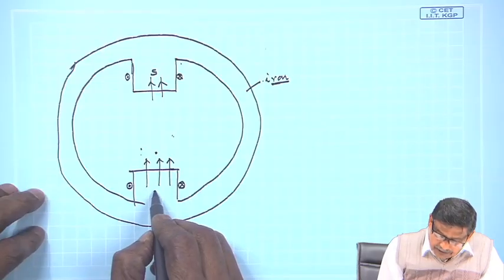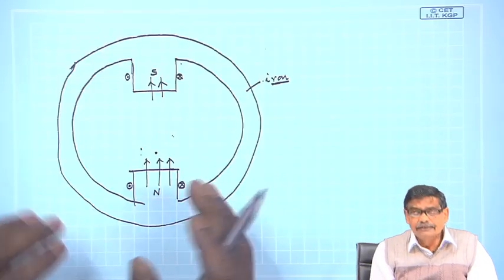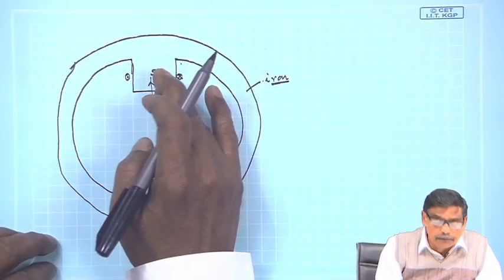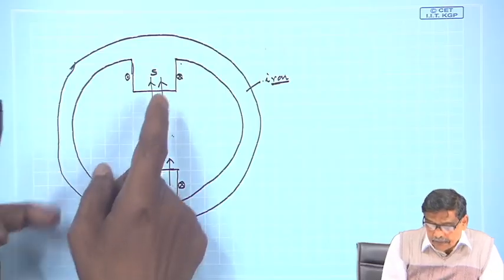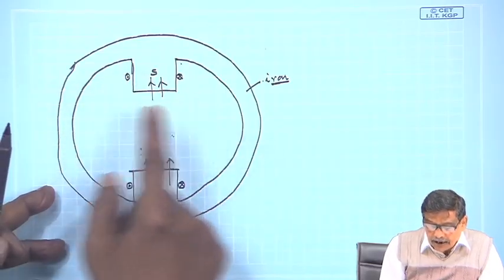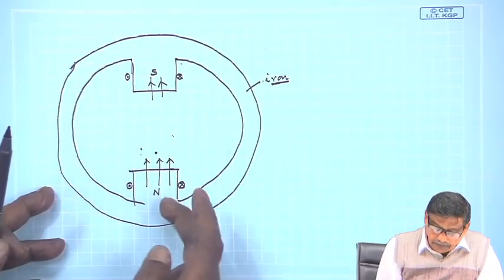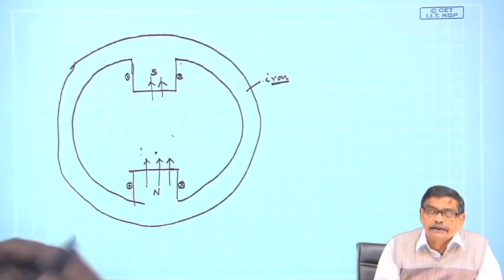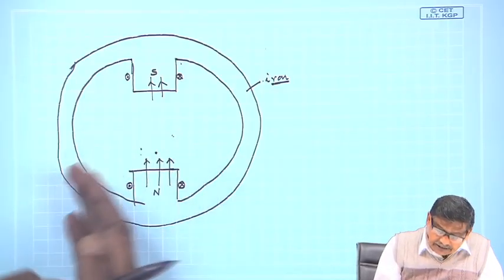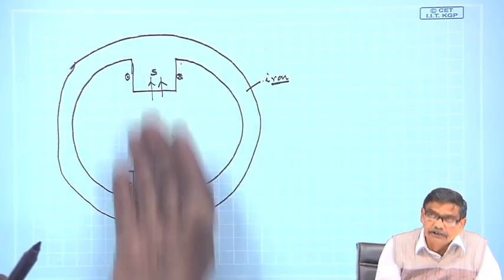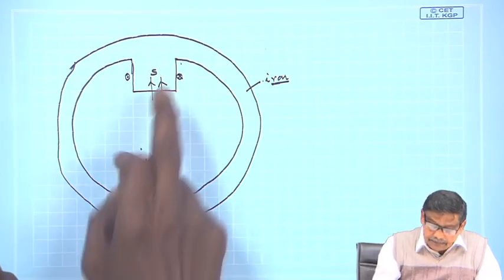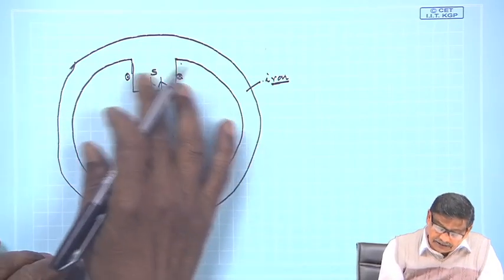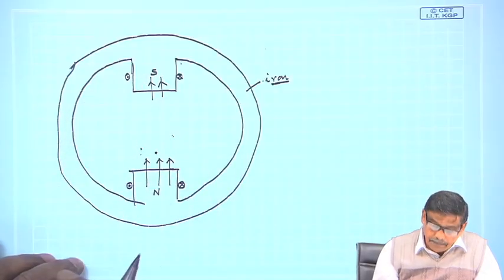So, this will behave like a north pole. In essence, these magnets could be permanent, but they could also be electromagnets, by having coils wrapped around the projected poles and passing some DC current. Here the advantage is you can change the strength of this field by varying the magnitude of the current. So, this is the scenario I make.